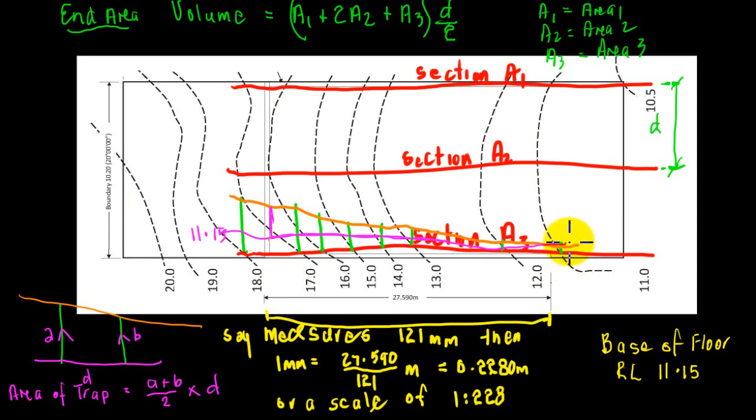So wherever that distance is from the front of our thing, we scale up 1 meter to 11, and then we measure the distance along to the 12 and scale up 2 meters to 12, scale it on to 13, up 3, and so on till we get through to the end, and we can create a section or a representation of the natural ground level.